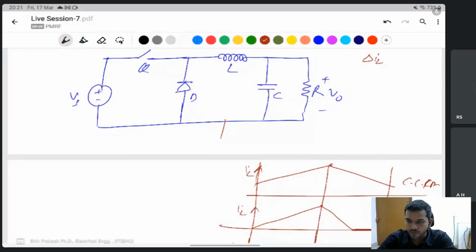You know about the motor. In an electrical motor, when the switch is on, at that time the starting current will be 5 to 6 times the full load current. Observe this one. In an EV, an induction motor is used, and a battery is present, but the battery has some limitation in delivering current, because a lithium ion battery is used.